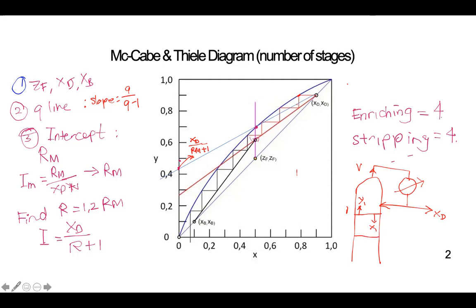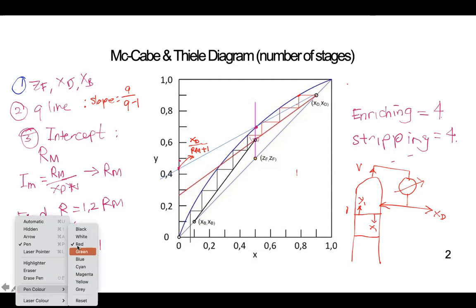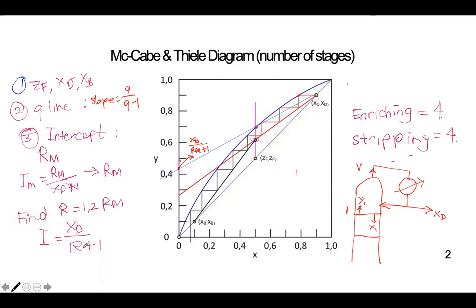Now, Kevin, how do you find the composition of the vapor leaving tray 2? The second triangle, just drag it to the left. Then you go to the operating line to get these points. Look, this is in pairs: X pairs with the Y2.